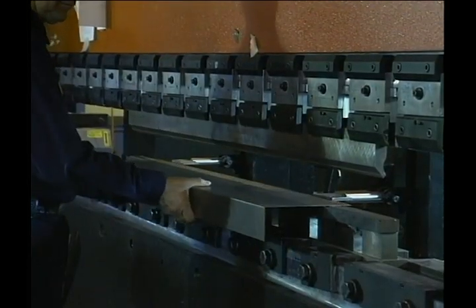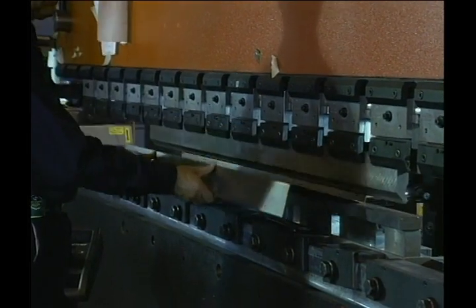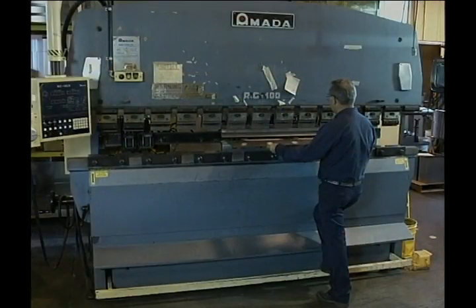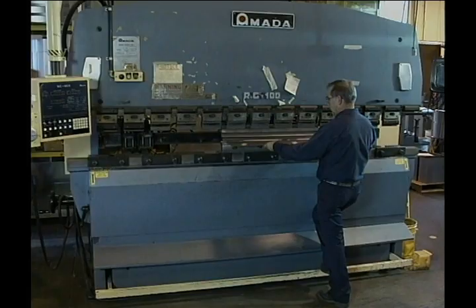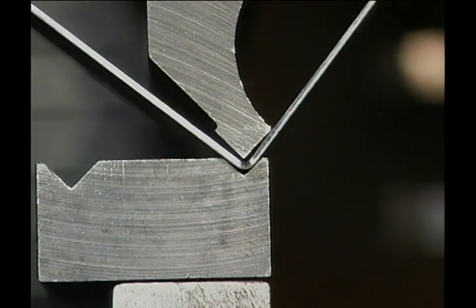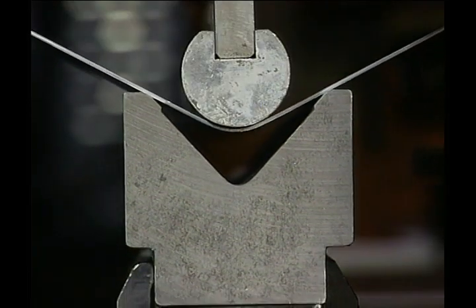In a typical press brake bending operation, a piece of metal is placed between the upper and lower dies and formed by means of the force and pressure exerted by lowering the ram. On some press brakes, the ram and upper dies remain stationary, while the bed holding the lower dies provides the force that bends the part. 3 contact points are involved in a bend: the tip of the punch and 2 points on the female die. The material is bent to the desired angle as the punch enters the die. The larger the die opening, the smaller the force required to form a given angle.